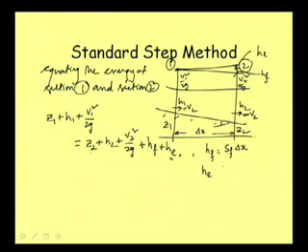Then the eddy loss can be written as some factor k times (V1 square minus V2 square) divided by twice g. So whether the velocity is more here or less here does not matter, we need to get the difference. That way this expression can be used for eddy loss. And then experimentally it was studied and it was found that this k value we can use as 0.1 to 0.3 for a contracting channel.